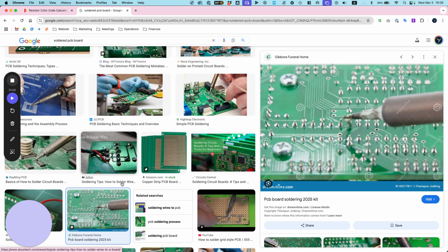I'm actually not going to snip the wire yet. I'm going to keep the whole thing there. It's just easier to work with. Okay, this is the side where the component's going to be, and this is the side where all the solder goes. That's another thing. You want to stay consistent. So I'm just going to go Q3 right now. Q3 is right here. I know it's hard to see, but once I start soldering, you'll see which one I'm working with.